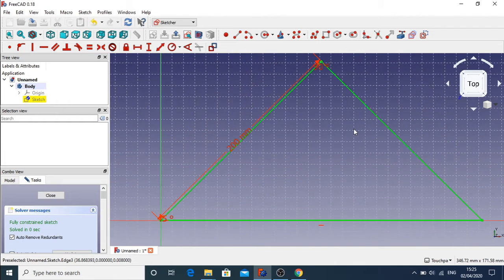So there we have it. We have our guide already done. We've got our triangle, so 45 degrees here for the 4 slots that I want, and 200 millimeters radius. This will end up being the length that divides it: one side to the left here will be your Geneva wheel, and one side to the right here will be your actual pinwheel.